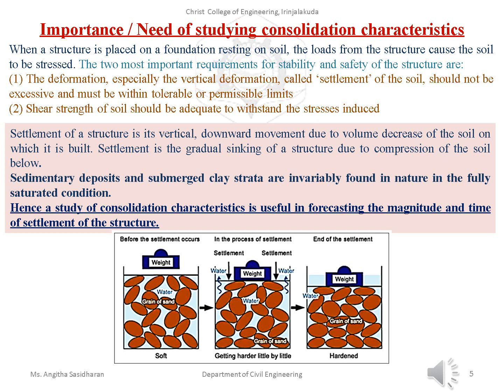The two most important requirements for the stability and safety of the structure are, first, that the vertical deformation, called settlement, of that soil should not be excessive. It should be within some tolerable or permissible limits.